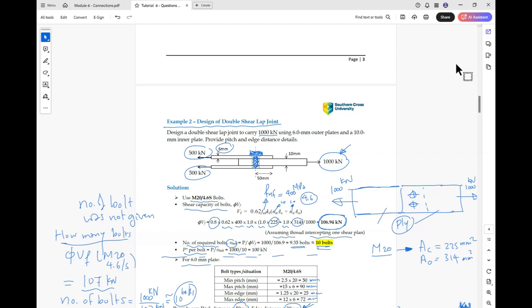After you get the bending moment, it will be similar to the normal procedure. Just get the maximum moment on the rafter and use it to design the rafter and the column, and so on. Okay, great.